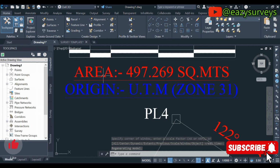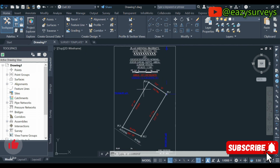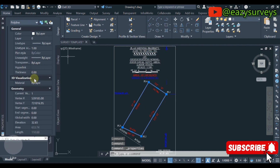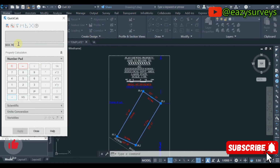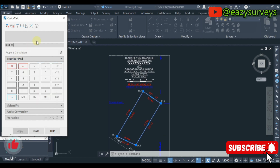Remember, you need to put the area, okay, of this property. So it's very easy to do. Just click on the perimeter boundary. Alright, remember this is a polyline, so when you click on it, it's going to highlight the whole of the polyline. You right click and you come to properties, and you can scroll down, you are going to see its area. So this is the beauty of the 3D as well. So when you click on area, click on this calculator icon here, then you highlight it, then you right click to copy. So the default area is the square meters.